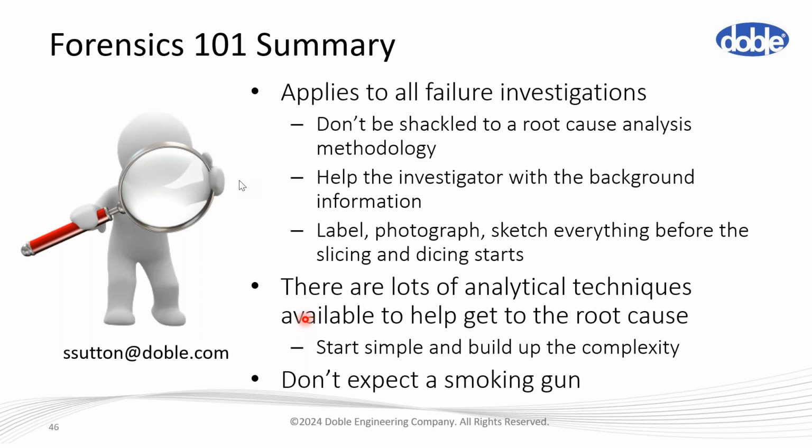What would I consider to be excessive circulating current? That's going to be in excess of what it's designed for. Again, depending on the voltage level of the cable, you're going to have all sorts of different earthing arrangements, whether that's single point, double point, cross bonded, and so there will be an expected circulating current for a particular earthing arrangement. But if you want to follow up, I've left your email address, so I will send you an email later.